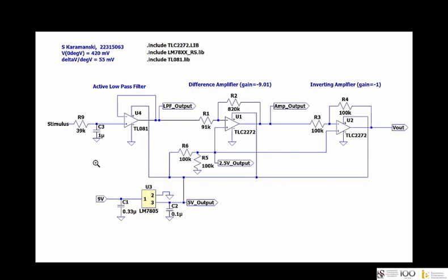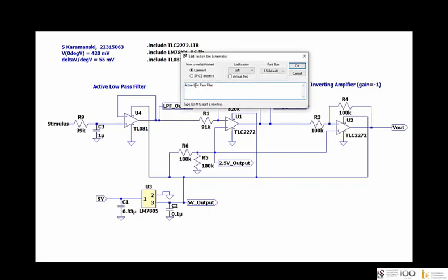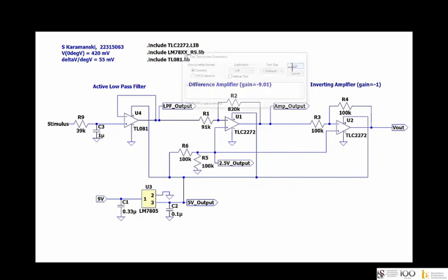Yep. So just for clarity's sake again, the reason you don't have a buffer between R5 and your U1 op-amp is because the op-amp does not have a current flowing into it. Its impedance is already infinite. If there were resistors, let's say I had resistors over here, then these resistors and those resistors would obviously mess with each other. Like there would be some differences. So I would have to add a buffer here.